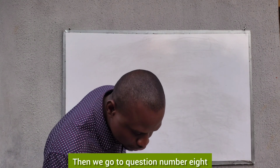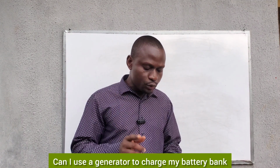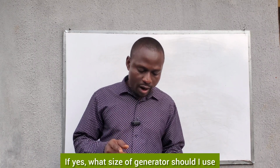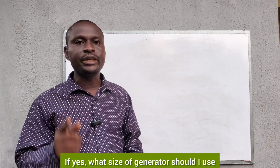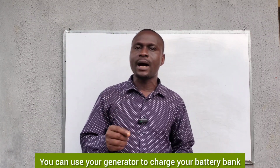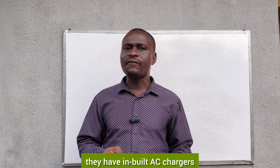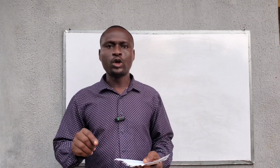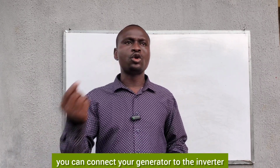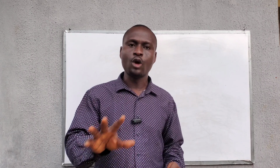Then we go to question number 8. Can I use a generator to charge my battery bank? If yes, what size of generator should I use? You can use your generator to charge your battery bank through the inverter, because most inverters have inbuilt AC chargers. So you can connect your generator to the inverter, and you can use that generator to charge your battery bank.